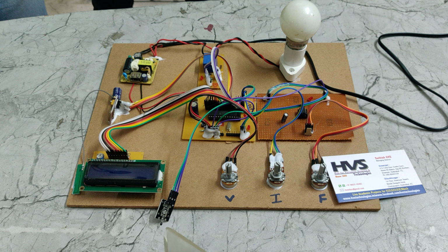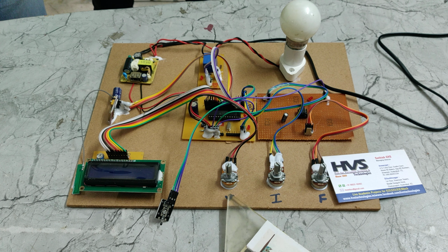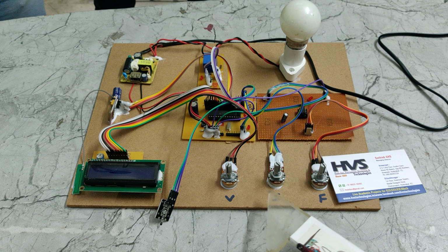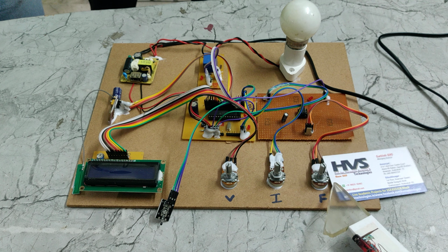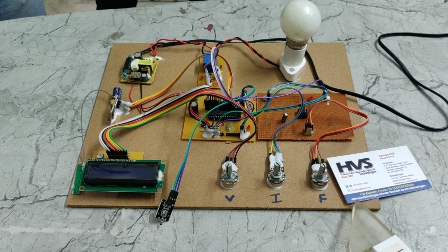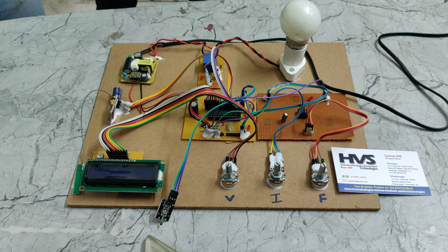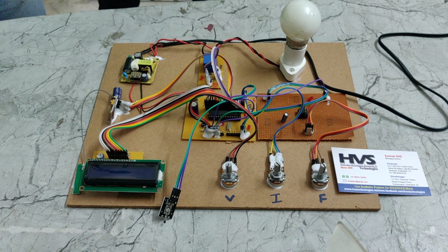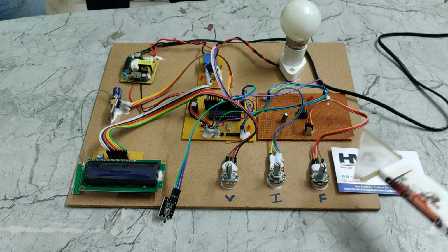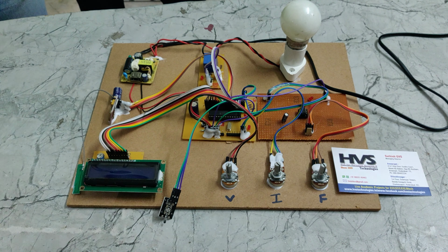The system continuously monitors four major parameters: the voltage coming out from the grid, along with the load, how much load there is on the particular grid, the frequency coming out from the grid generators, and the temperature near the generator or feeders. These four parameters are the main ones to check the quality and maintenance of the grid, and they are continuously monitored by the PIC microcontroller.